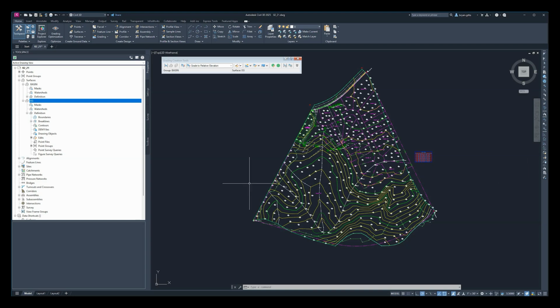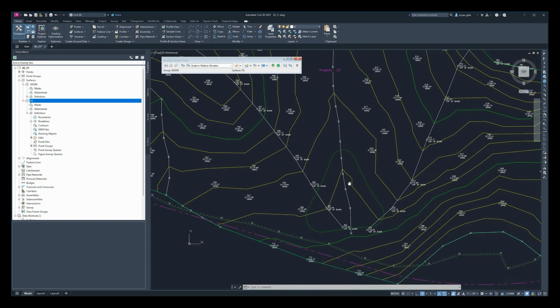So let's go ahead and zoom in down here, kind of to the southwest corner. We have this nice green contour line, or this feature. Zoom in around that. Then on our toolbar, we're going to finally come into our create option. And we're going to open up this drop-down menu, and make sure we have create grading turned on. That's going to automatically activate the tool.